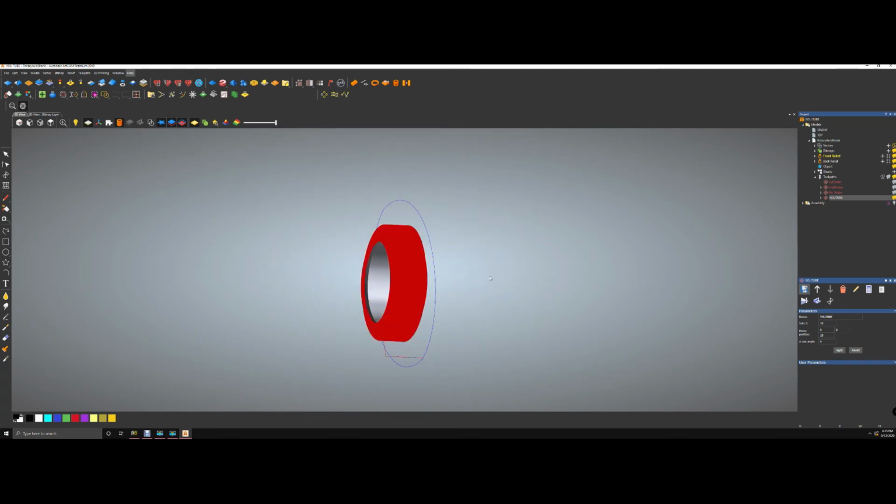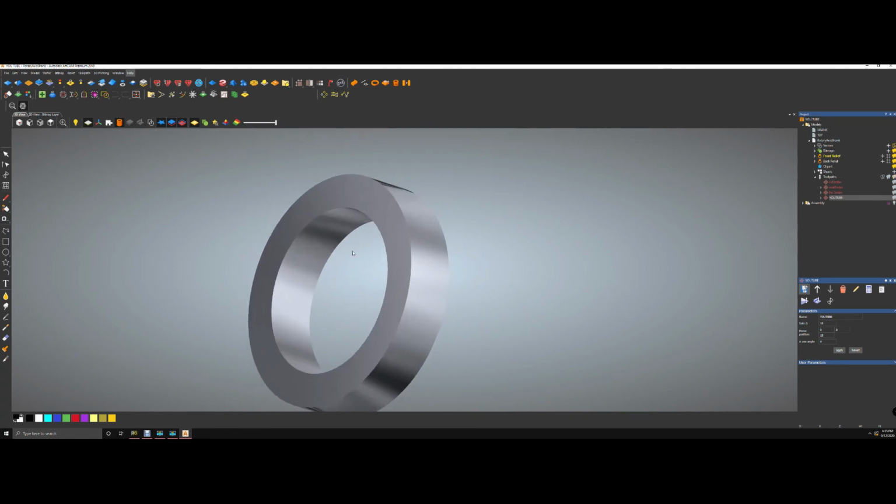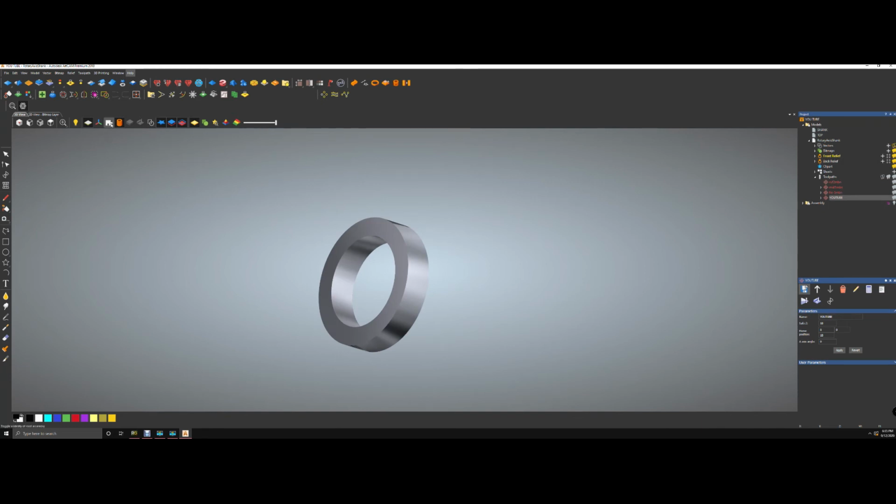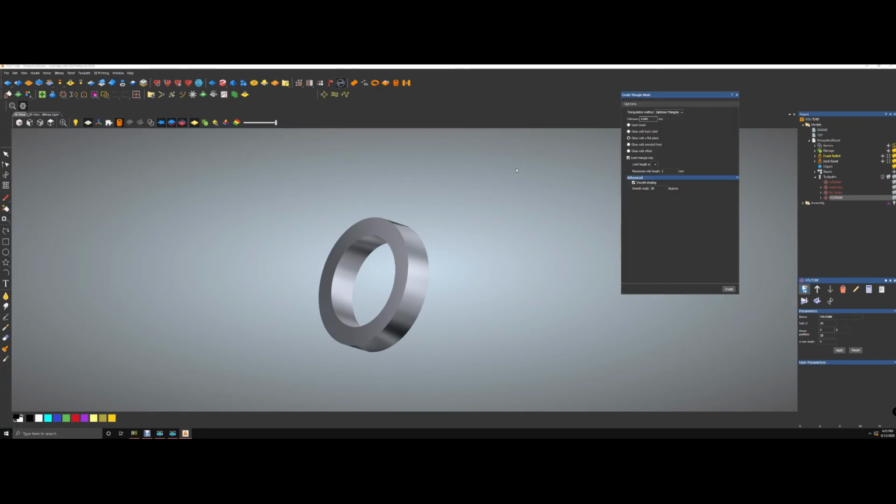It's very important. That's strictly for milling. Now, if you want to do 3D printing, so let's say you shut this before, you need to add this to the actual model. So let's go back. Usually when we add it, we go to this here to create triangle mesh. It's very important. So we're going to create the triangle mesh. Let's call this YouTube.